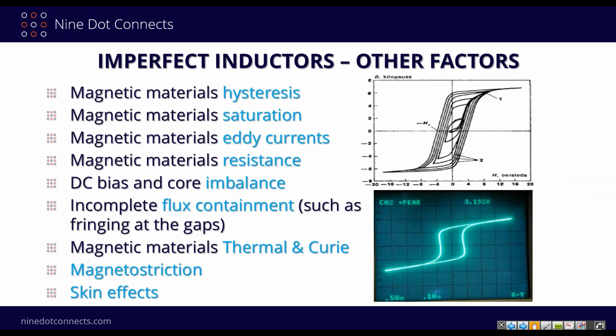Magnetic materials, they have hysteresis. Hysteresis means that when you apply a current to something by moving to the right of the curve, the lines go up. Eventually, it tapers over, and then you go to the left. The current changes and goes the other way, say in a switching transformer, back and forth. It goes up and to the right, and then it goes over and down to the left, and then it goes back and up to the right. And every time, a real inductor traces out a curve. That's because there is some hysteresis in there, that the going up and the coming down do not occur on one exact line. They're separated, and as a result, energy gets stored in there.